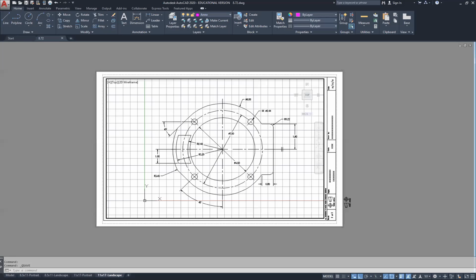Let's look at our sheet. It looks like everything is in here presentable. Now all you have to do, double click into the gray area, making sure not to change your scale. Double click on there, you can see what your scale is. Should be still set to 1 to 1. Double click on the gray, get out of the viewport.